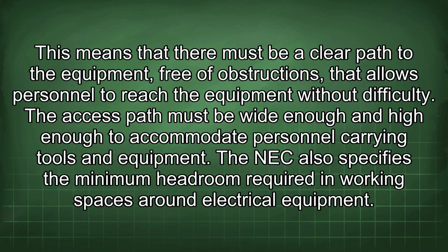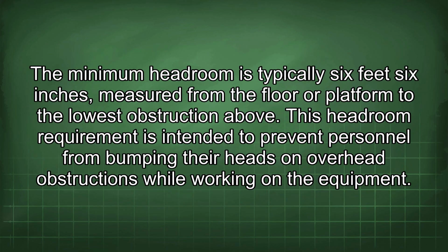The NEC also specifies the minimum headroom required in working spaces around electrical equipment. The minimum headroom is typically 6 feet 6 inches, measured from the floor or platform to the lowest obstruction above. This headroom requirement is intended to prevent personnel from bumping their heads on overhead obstructions while working on the equipment.